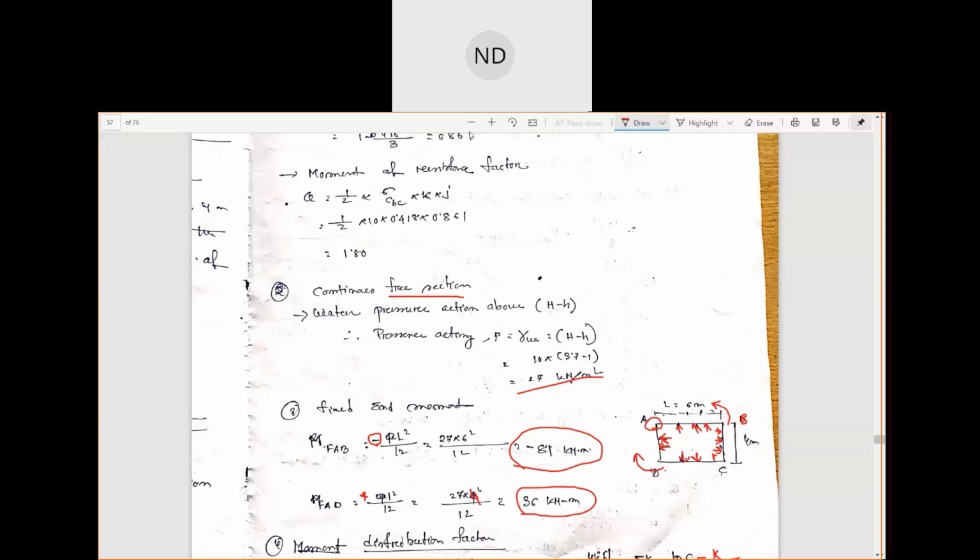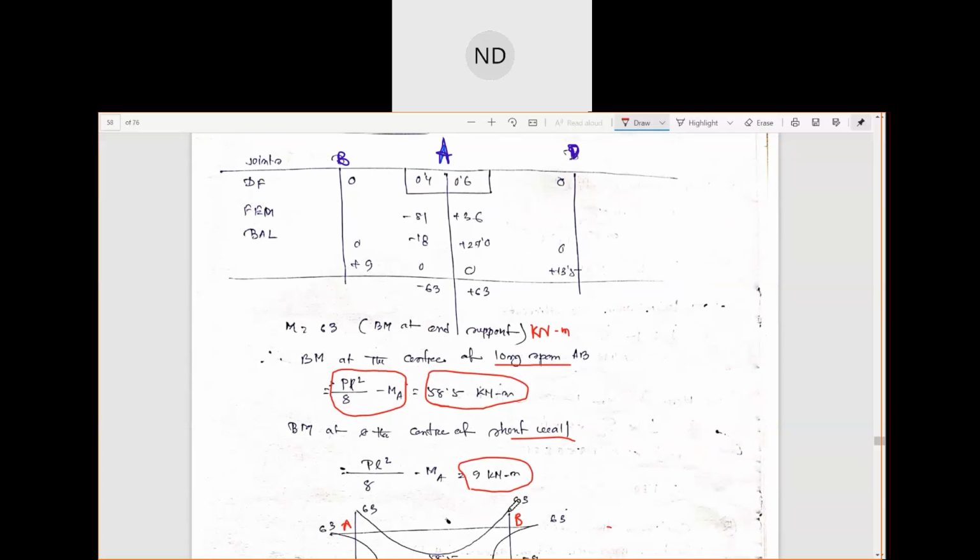Okay, sorry. Then we have what? We have considered this longer wall, but why are we taking this shorter wall dimension, B? Because we are finding out the tension here in the longer wall. So when we are finding out the tension in this longer wall, this is due to the factors on the shorter wall. Because when this pressure comes here, this shorter span is going to be affected. So therefore we always take the shorter span.